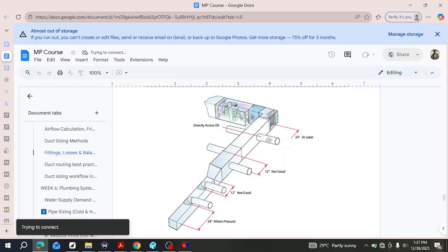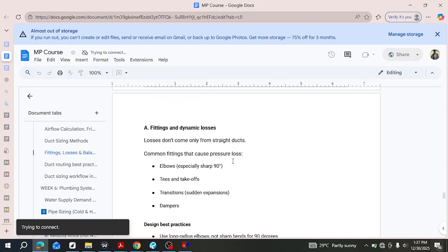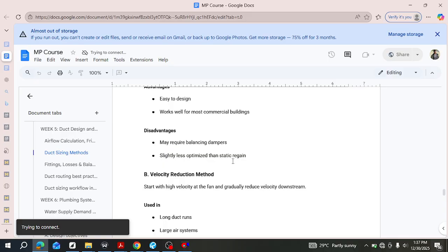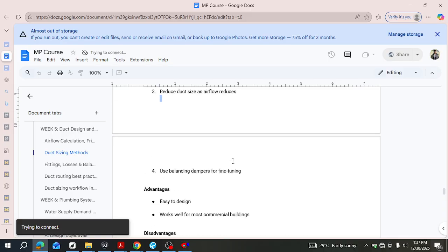So the whole point of having a damper inside these ducts, right, is to slow down or to stop the air flowing in here, so that the air now is in a channel to another place. That is what the damper does, right? Some of them are smartly controlled in the sense that they're automated, as we talked about with energy standards some time ago, so that as it's not flowing here, it's going to go here. So the system is just automated in that manner. There are different types of dampers. So balancing in this case just helps to ensure that there's proper distribution of airflow from one point to another, right?